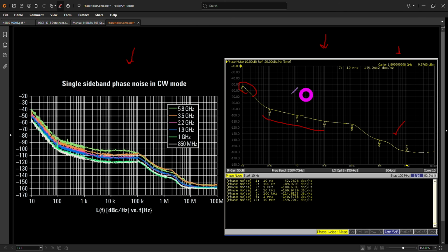I should also probably go back, open it up, and really tighten the chassis and the shield, bring it down, make sure there's nothing that's deviating these. Remember, these numbers are already pretty small, so you can imagine that even a very, very small amount of leakage and problems in the loop can introduce this. Now, I think from the shape of this, it looks like the loop filter band is around here or so. So this really is the reference multiplied up, so it should be pretty good. And there might be some aging effect on that as well.